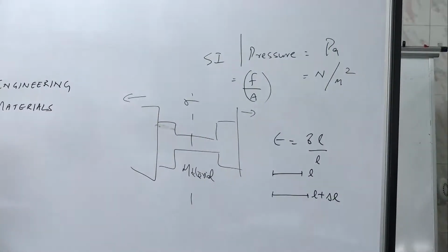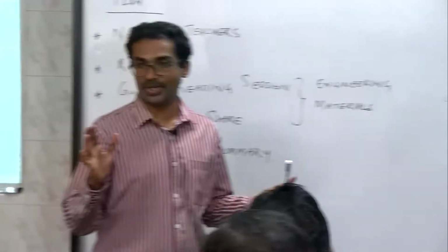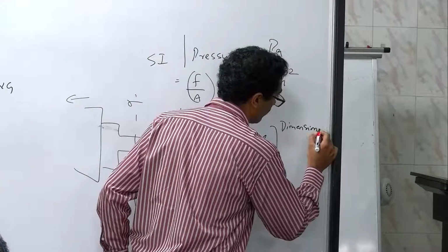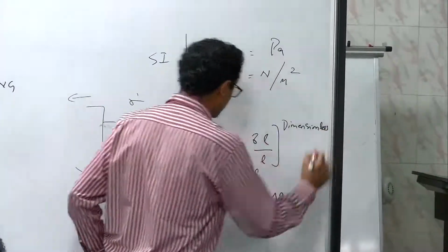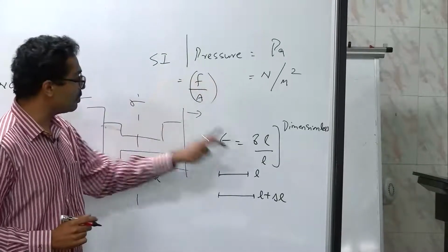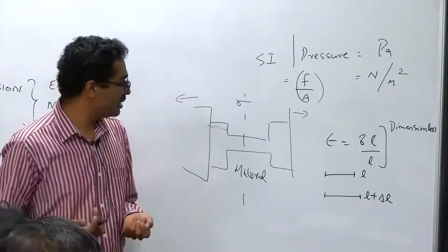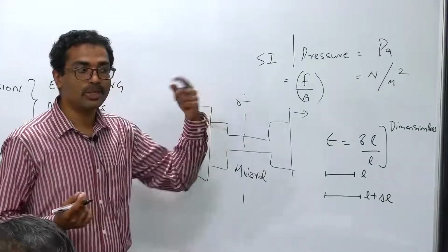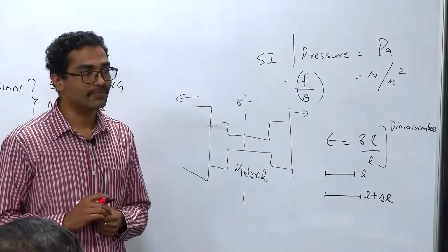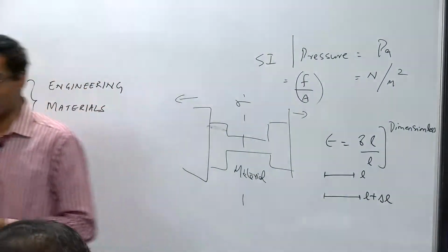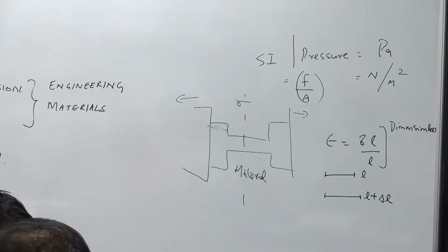By looking at this formula, can you tell me what the unit of strain is? It's perfectly dimensionless, right? So this is a dimensionless quantity. So if this is a dimensionless quantity, the stress by strain, what will be the dimension of that? Again Newton per meter square, and hence the unit of Young's modulus is pascals. Okay, here it is 40 to 400 gigapascals typically for metals. Alright.